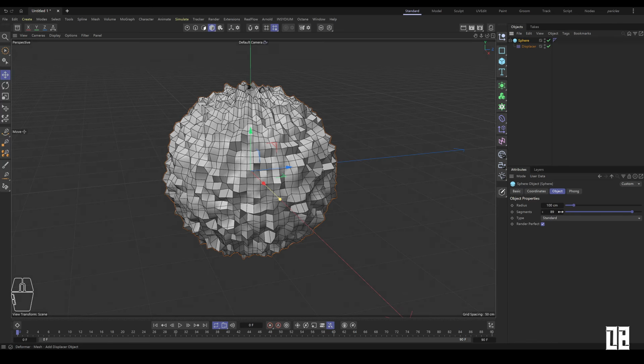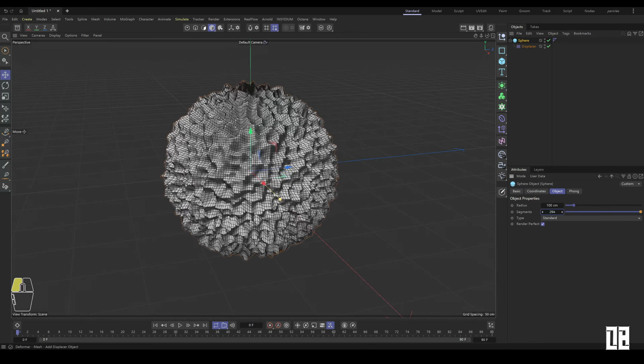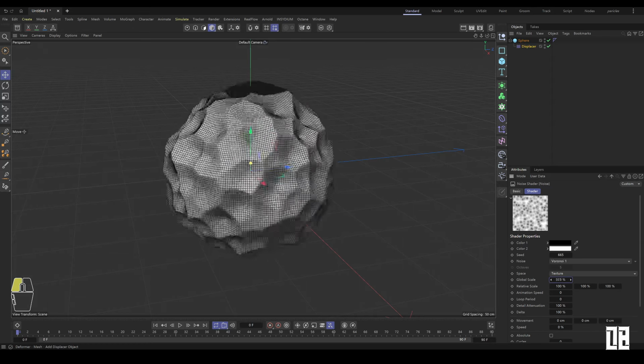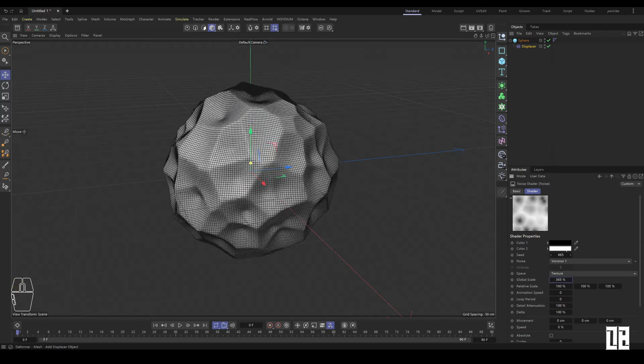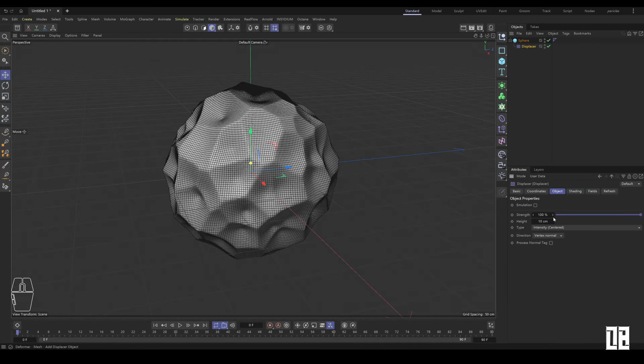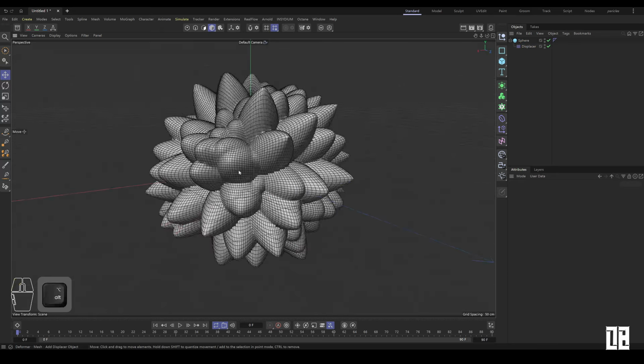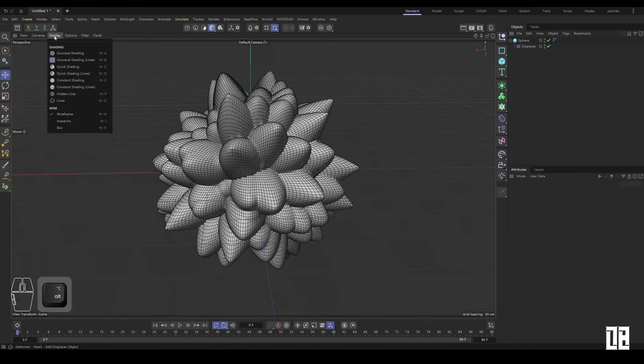The number of polygon faces in the model is not enough, and the accuracy needs to be improved to see better details. Adjust the size of the noise and the displacement height, which can be negative. After simply adjusting the parameters, you get a sphere with a displacement effect.